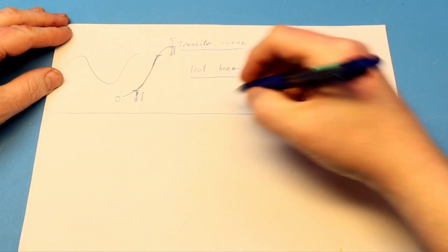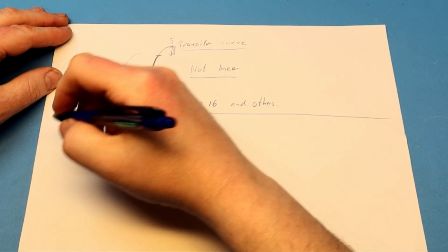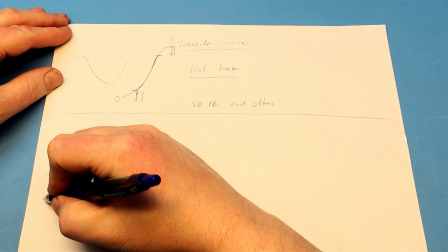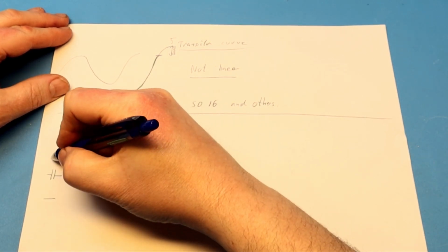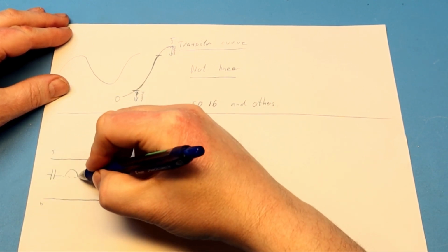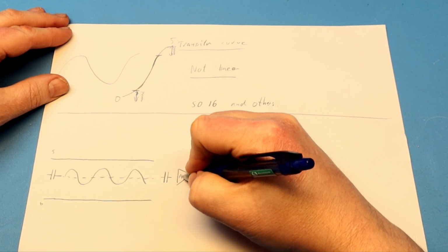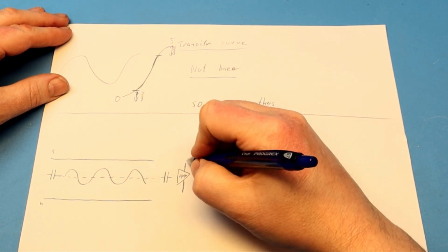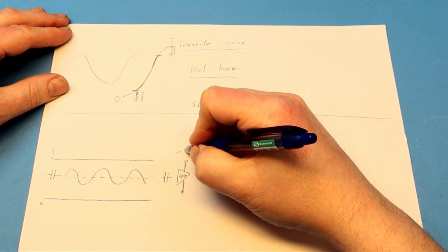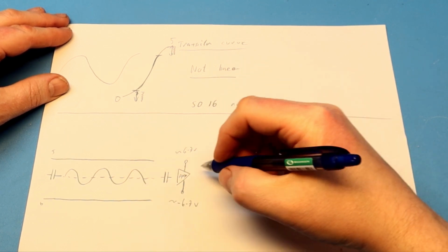The way the Sound Blaster 16 and other sound cards solve this, they don't use a symmetrical power input at all. They use the 0 to 5 volt rail. But on the input stage, that's less of a problem because you can live with the kind of distortion that you get on the input, because the input signal on a typical line level is either 1 volt peak to peak or 2 volt peak to peak maximum on a line input. And within those boundaries, it's possible to do it between 0 and 5 volt.